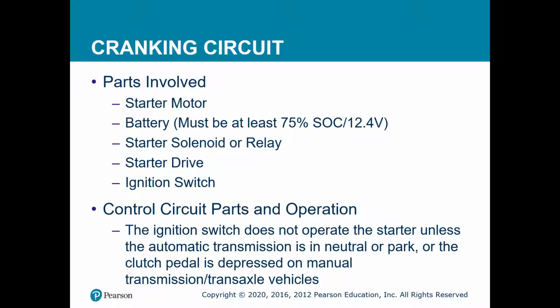An important item to note with regard to how we control the starter is that the ignition switch itself does not operate the starter unless certain safety functions have been followed. So in an automatic transmission, it needs to be in either neutral or park. And if it's a manual transmission, obviously the clutch pedal would need to be depressed.